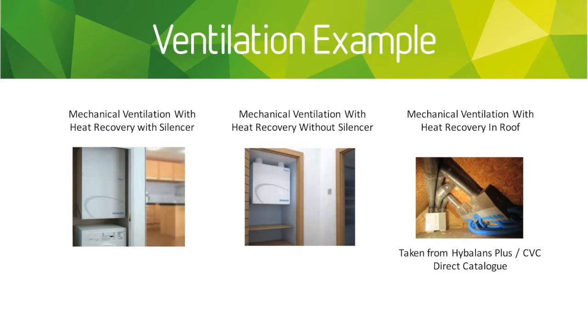I would recommend it be located in a cupboard, as do the manufacturers, purely because this is a unit that needs to be maintained. They will have to have the filters changed periodically throughout a year, depending on your environment. Most likely it's probably about once a year, it needs cleaning. If that's up in your roof space, it's likely that you won't do this, or it could be relatively dangerous, as you'll fill your roof with pretty much junk. It's just being realistic, putting it in a very easy, accessible place.